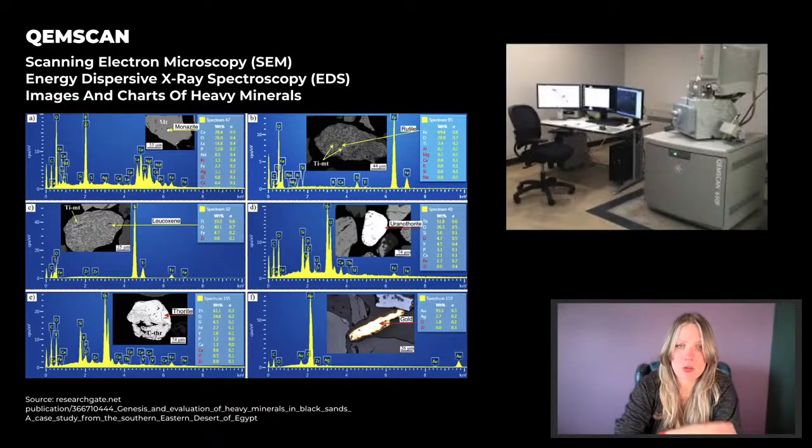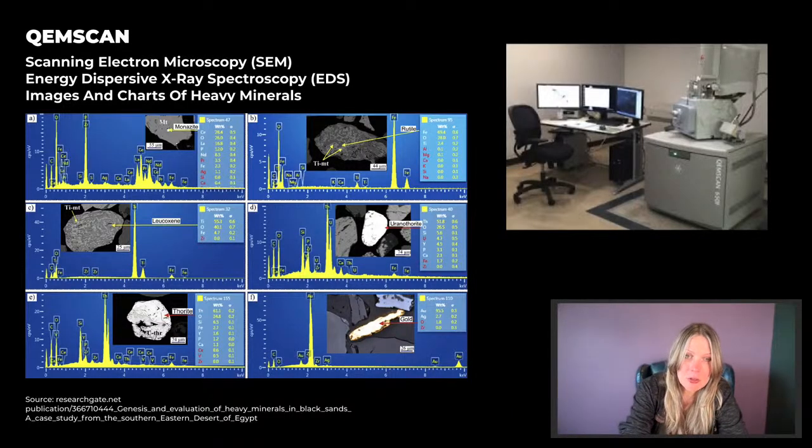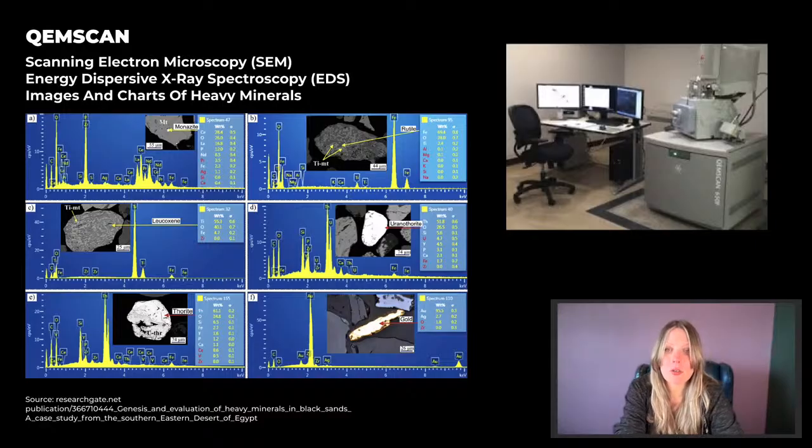It begins with a raw sand sample, which is first washed, then dried in an electric furnace and weighed. From the dried material, a portion is selected by quartering, weighed again, and then separated in heavy liquids until all of the light fraction minerals are removed. The heavy mineral concentrate is then carefully washed, dried once more, and weighed. This process allows us to calculate the yield of heavy mineral concentrate per ton of rock.